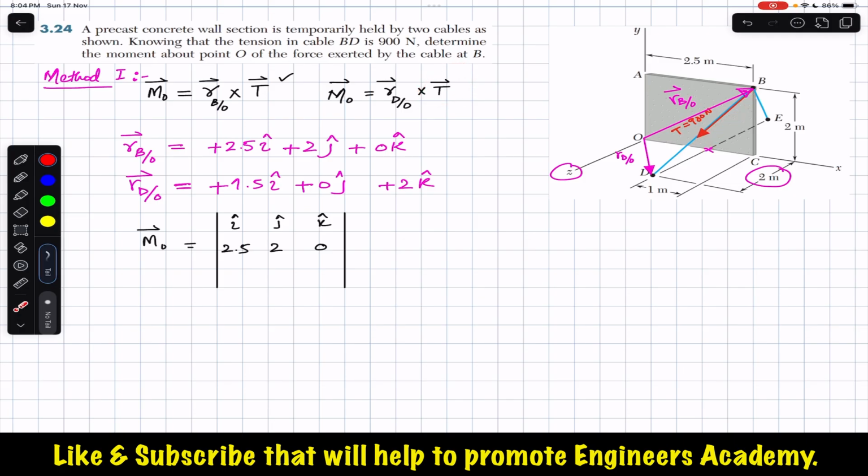So we need to write T in terms of its x, y, and z components. For that, we have to find the T vector. So T vector is equal to the magnitude of the T times the unit vector from B to D, since this T, the tension at point B, is acting from B to D. So the unit vector is from B to D. Similarly, the magnitude is given, which is 900, and the unit vector is the position vector from B to D divided by the magnitude of that position vector.